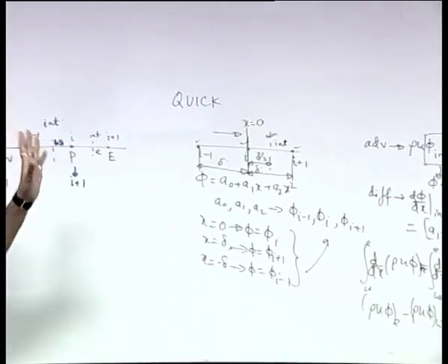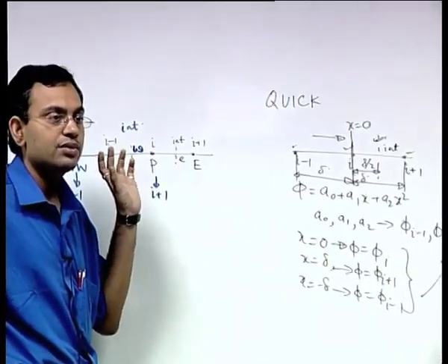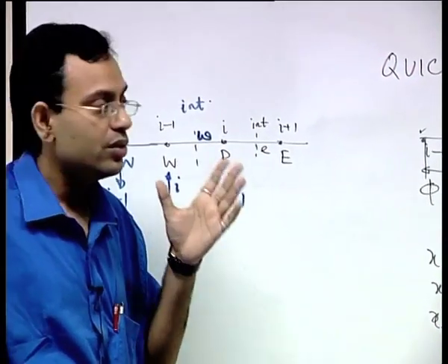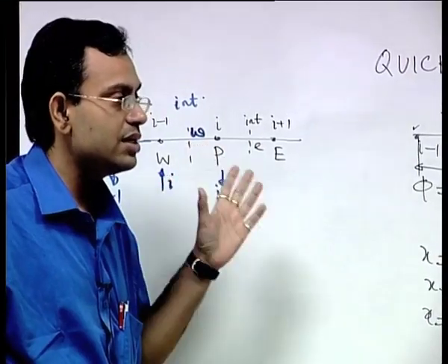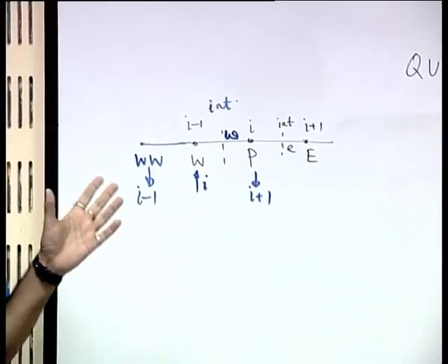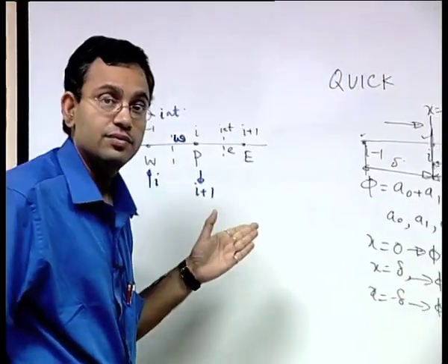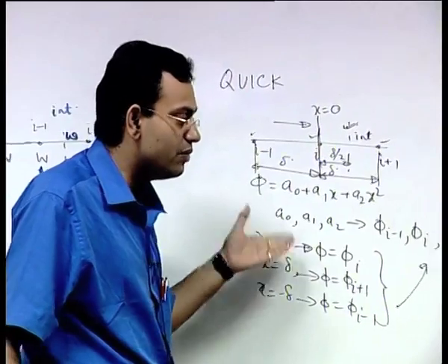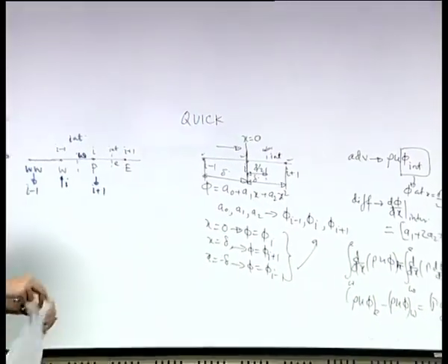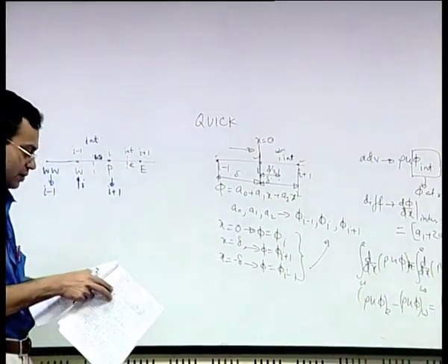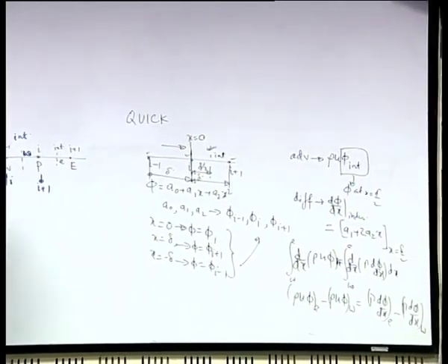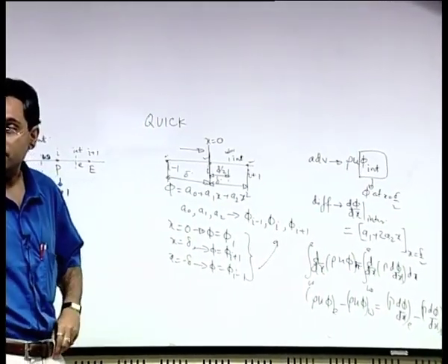If some of the coefficients are negative or of opposite sign than the other coefficients, then you have to conclude that the scheme is conditionally stable, and you can find out the corresponding stability criteria. From the basic rules, it is simple algebra remaining after this exercise, and you can extend this. So the next part of the question is to extend the derivations to the one dimensional unsteady state convection diffusion problem with fully explicit time discretization.